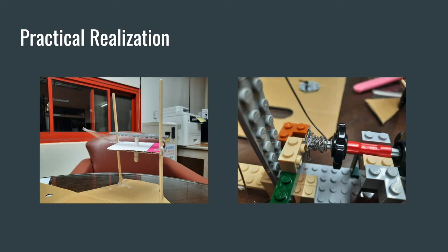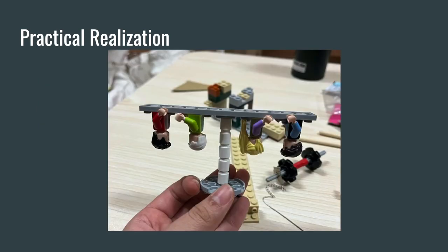For the front part, we have finished the basic structure of our clock, and several uncertainties made it inoperable. We moved on to the next step: fix the upper part of the pendulum, add bearings, and add loads onto it. It was difficult to decide how high we should fix it, because we have to make sure the legs on the lower part of the pendulum could match the teeth.